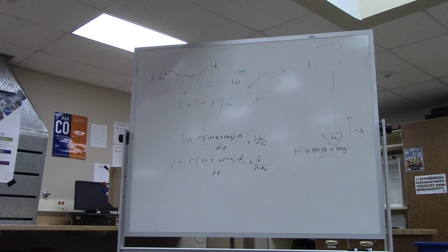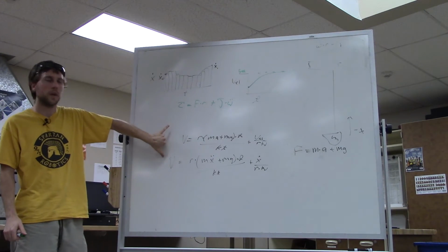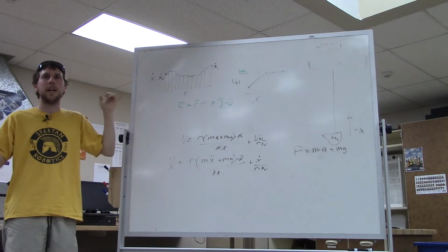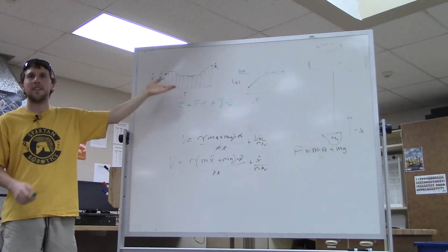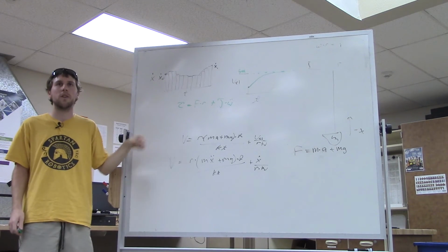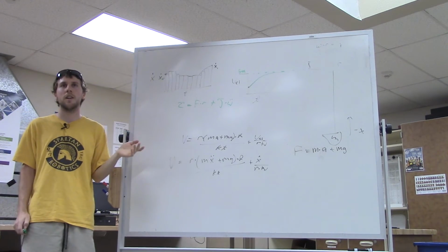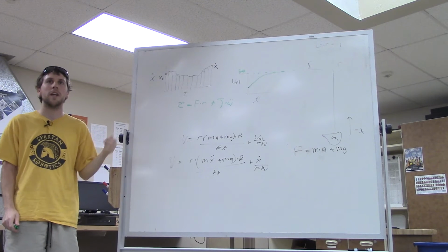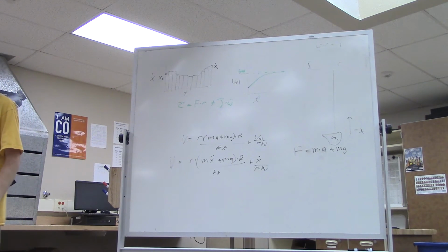But the really cool part is we can take our model here, hook it up to our PID loop, and try it on your laptop and see what happens. And then the really fun thing to do is to fiddle with your model and say, oh, I thought it was 10% heavier than it was, or 10% lighter than it was, and see how well your loop performs. And actually, there's an industry term for that, and that's called the gain margin. It's how tolerant you are to errors in the magnitude of the response.